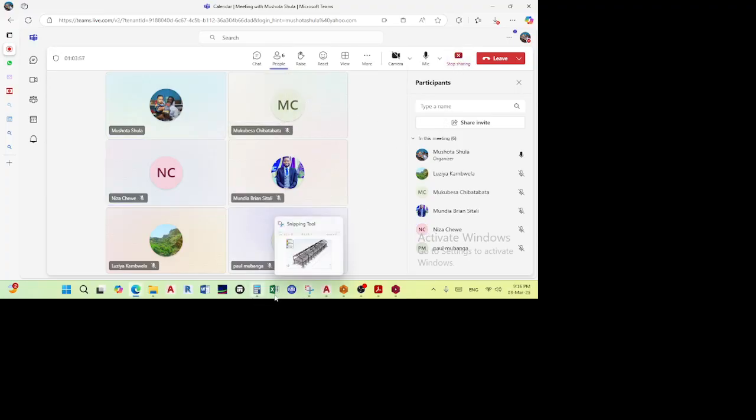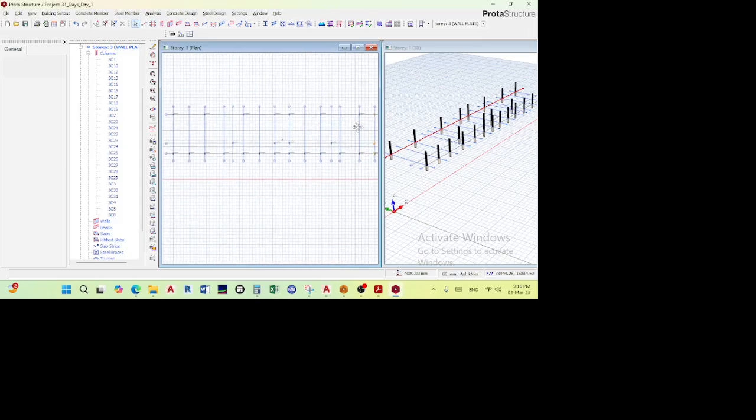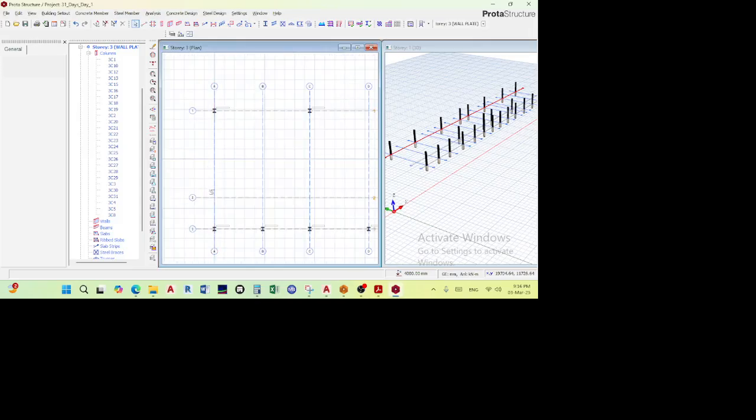So going back to my program, also, general rule of thumb: you're placing your truss on top of the steel, right? And where is the position of your steel? It's on the wall plate, right? So bear in mind you want to place the truss on top. And then also there are two types of ways in which you can either design your own truss or you can insert the ones that come with Prota.